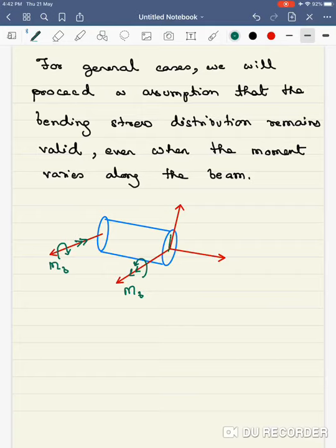If I had to create a positive shear on this face, then it would be oriented along this. So this is my V, and here it would just go downwards. This is V. In a more generic situation, this V is changing across the length. So this is a function of x, and by the way, this is just a dx element.